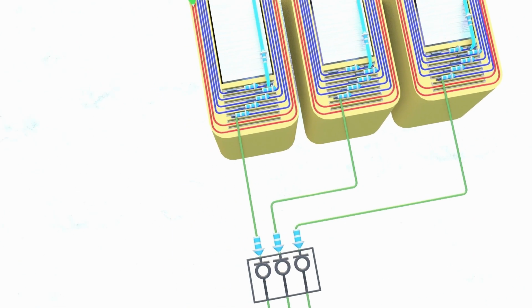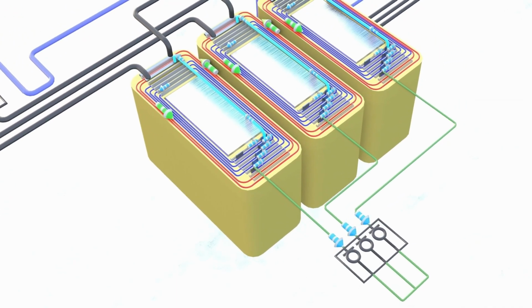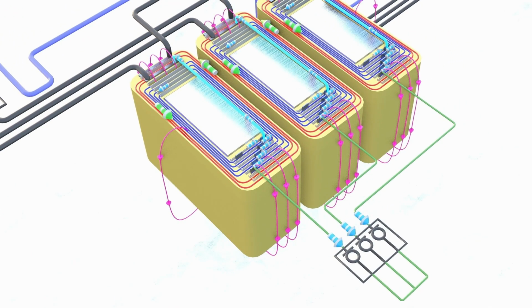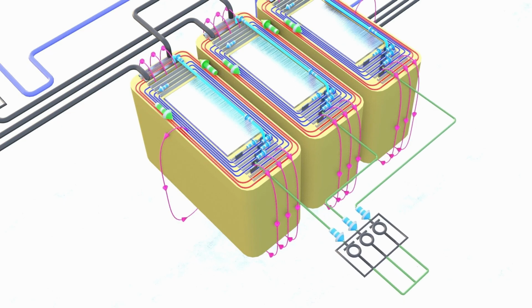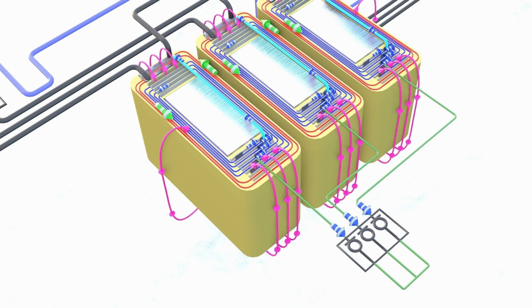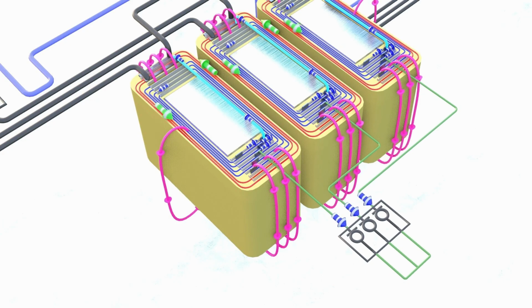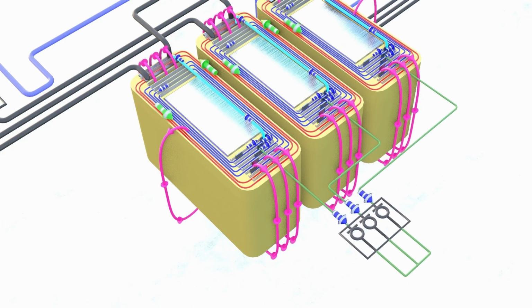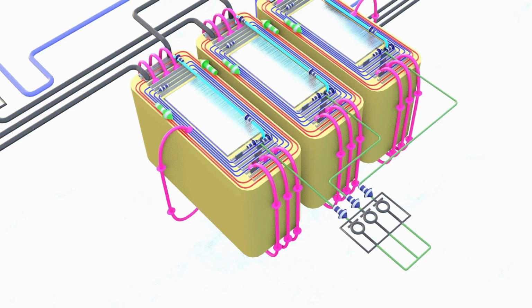Now let's examine the effects shown together. You can identify the primary current component depicted in green, the stray fields in magenta, generated by the air gap, the opposing current component of the secondary winding in blue, which is sent back to the input of the main coil via the winding tap and the newly introduced floating neutral point. You can make adjustments to the winding ratio by using the different taps on the secondary coils. So the inductance and the stray field component, clearly visible in the color magenta, are increased or decreased, thus varying the effect of the star point displacement.